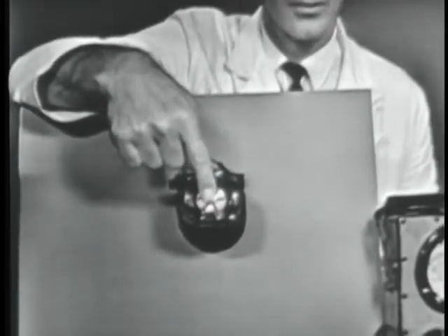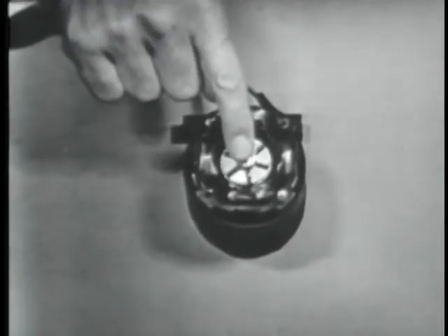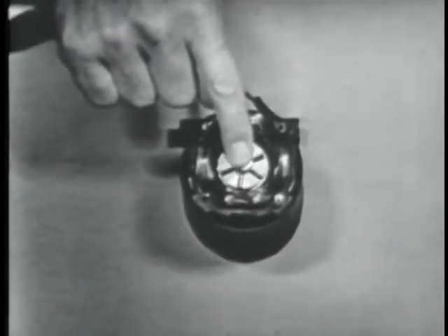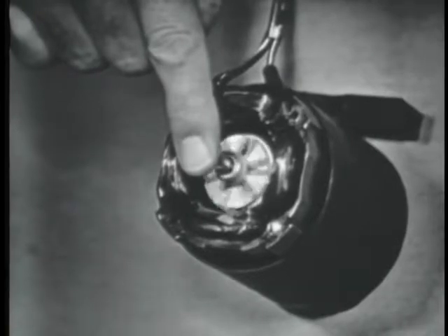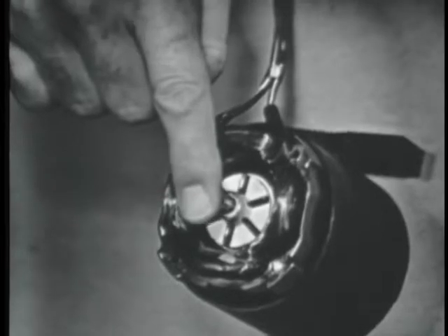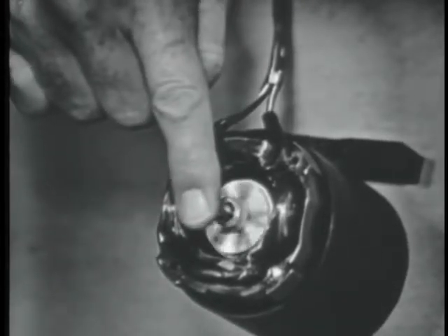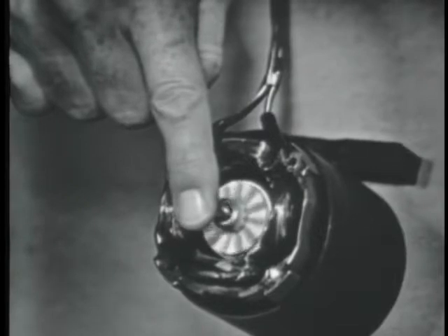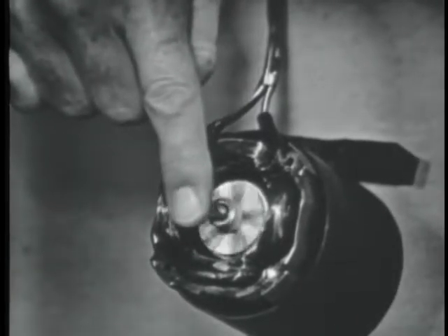The greater the frequency of cutting, the more current in the rotor, and the stronger the magnet. Now, that's why the rotor can continue to turn the fan. The load of the fan causes the rotor to slow down, just as I can do with my finger here. I can cause the rotor to turn slower. Now, as it slows down, the slippage increases, and the frequency at which the conductors of the rotor are cut by the rotating flux lines increases. More current flows. The magnet becomes stronger and compensates for the increased load.